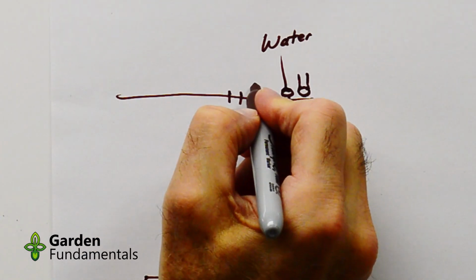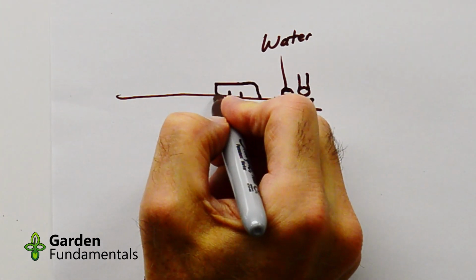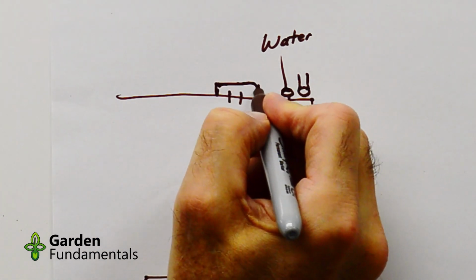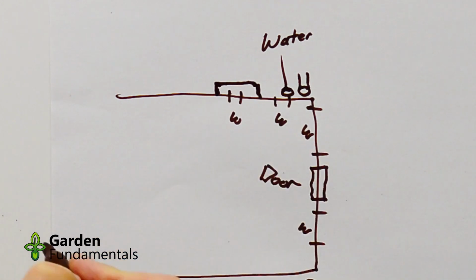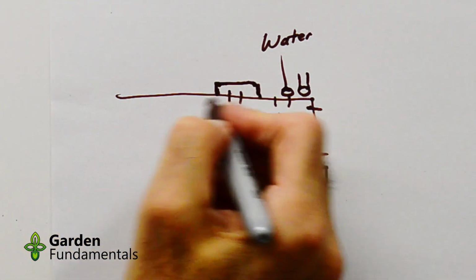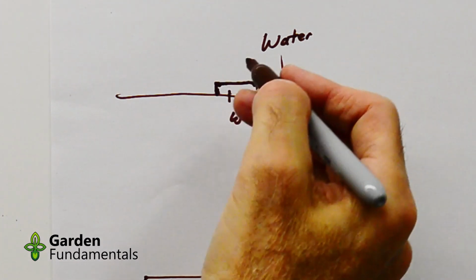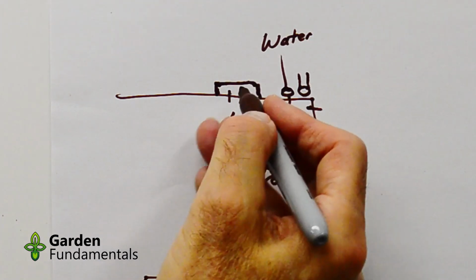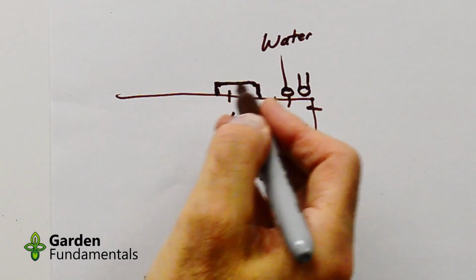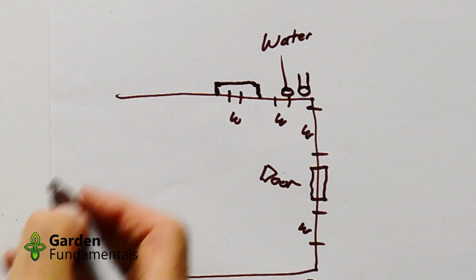In here there's a window in the basement and one of these wells that goes around the windows, so we can mark that in. We're probably not going to want to move that, otherwise we won't get any light into the window, and we might even get water running in there. So that's kind of a permanent fixture. We don't really want to touch that.